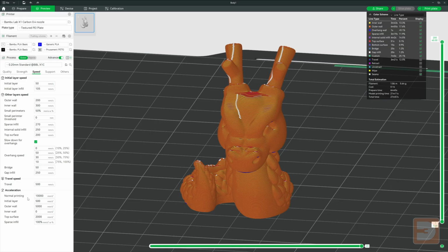Before acceleration was a real consideration for printing, printers would tend to jump to very fast speeds too quickly and cause print quality problems. But with these settings dialed in, it allows you to print at high speed with good quality still. I plan to do a deep dive into acceleration speeds in a future video where we can really look at what each of these does, but for most of you, you won't need to worry about this and can generally leave them as they are.